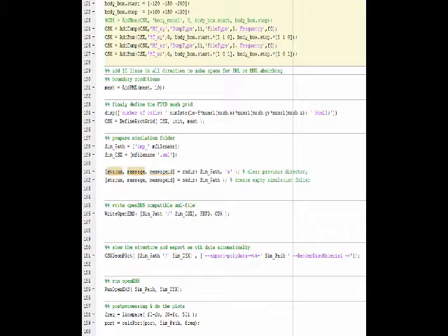After that, we override the CSX structure using addDump and addBox functions twice. One is in the x, y direction, the other one is in the x, z direction. In order to add 10 lines in all directions to make space for PML or more absorbing, we create the boundary conditions. Add PML is for adding perfect matched layers. We take mesh as parameter and override it again. To display this, we finally define the FDTD mesh grid structure using the function define rect grid and override